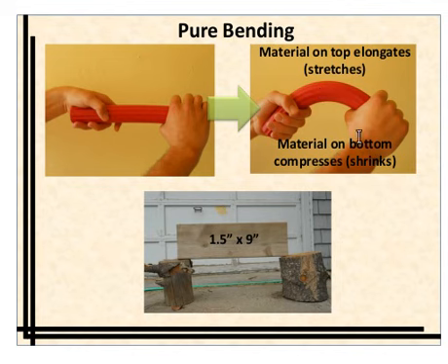An example of a beam that might experience this in your day-to-day life is something like a 2x10 that might have a load applied to it. It won't be in pure bending. If I was to apply a force in this direction, it wouldn't be in pure bending, but it would experience bending stresses.